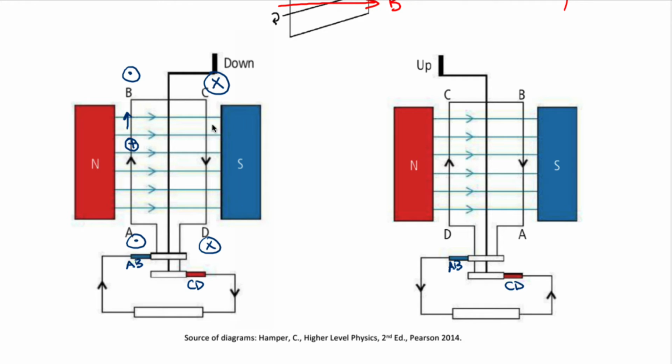If we do the same thing over here between CD, so take a positive charge here, it's now being forced by this mechanical turning that we're doing by turning the crank. It's being forced by that to go down into the page. Point your fingers therefore into the page, in the direction of the velocity of this positive charge. Turn your palm so that it's pointing to the right, and that again leaves your thumb pointing in the direction of the force. Here that force is downwards.